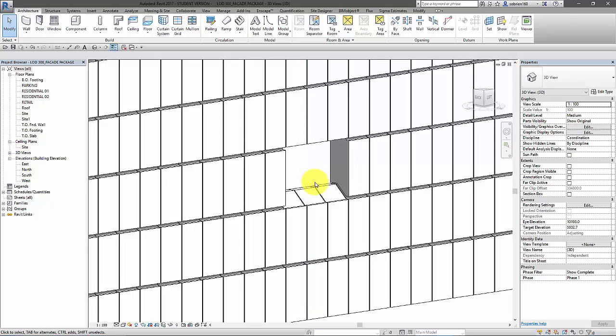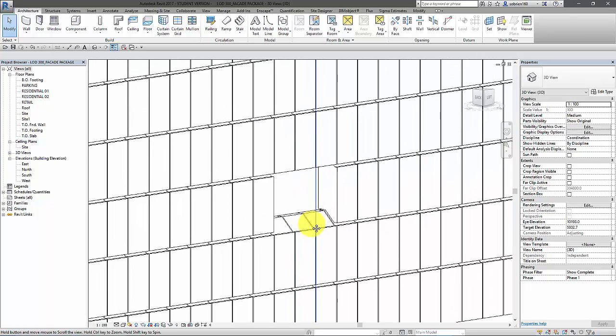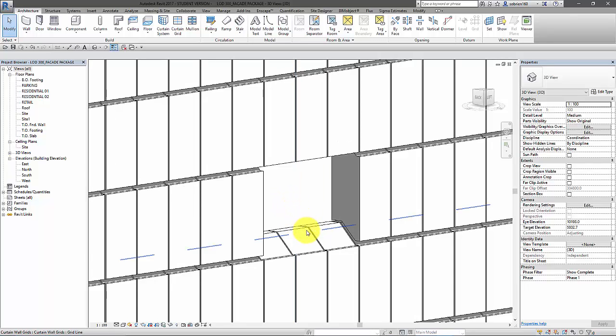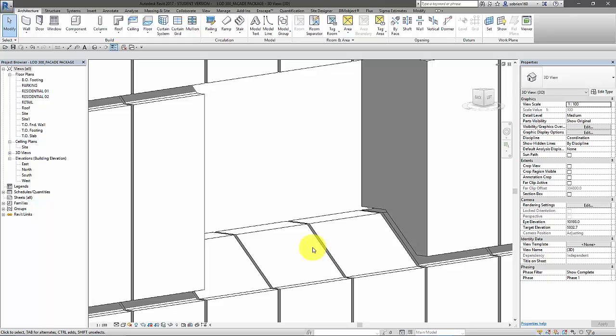So then all we need to do is create a curtain wall panel that has a window in it. So you make a generic curtain wall panel that has frames and glass and all the information you want in it. That means you can just plug it into your paneling system. You can add the flashing, you can add the window sills, you can add all that stuff as you go up in the level of detail, as you get through the whole thing.